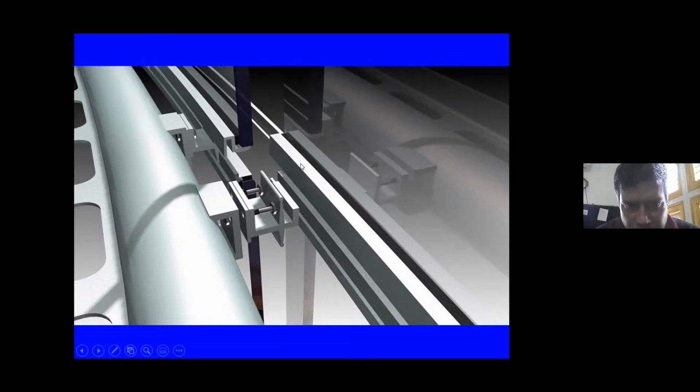This is the only place you can really see how the system works. You have this slotted system here, a U slot here, and a circular plate here, which accommodates this drift. And again, it's 2 to 2.5% drift. This is during the construction.